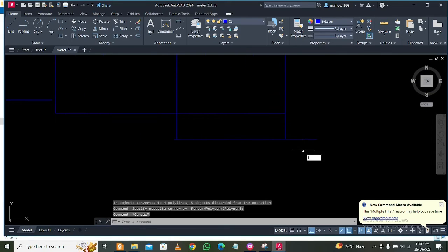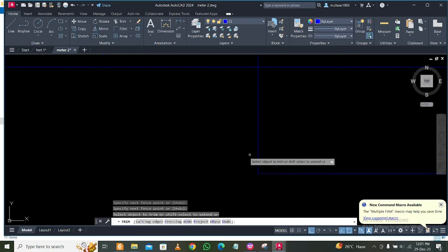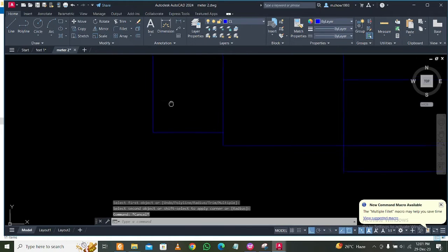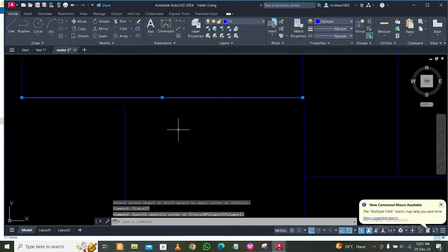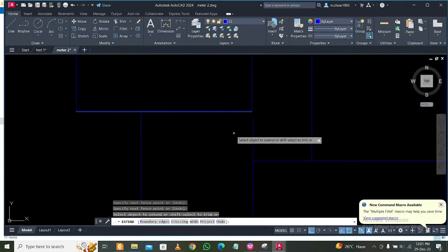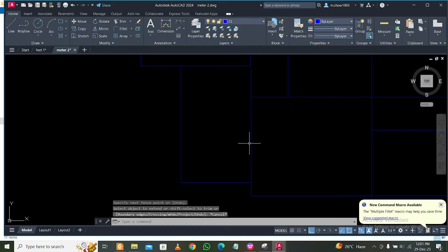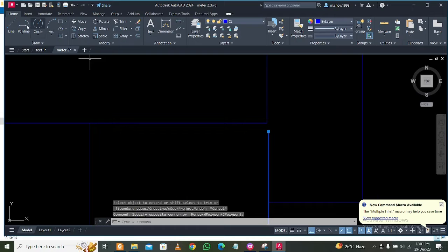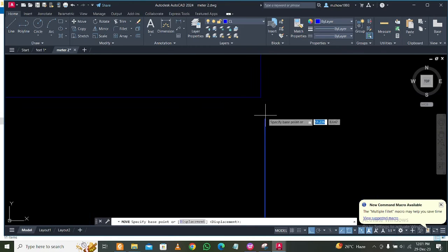So now this part, trim this, and obviously select this, EX enter, extend this, and F enter, fillet this, and then select this, EX enter, select this. Okay, this needs to be in the same line. I need to move this much, or okay, I think I'll move this, because this column is actually in a different location, but yeah, we have to move this just for this purpose.